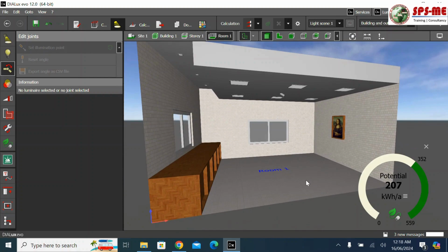So normally before you do the calculations, you need to set what lux you require. So I did not set that over there. If I did not set anything, by default it will select 500 lux. Otherwise you can go and select that. That we have discussed in the previous class. So you can go to the spaces, and from there you can select the utilization profile, and you can select what you need. Accordingly, whichever utilization profile you select, the lux will be selected. If you don't set anything, by default 500 lux will be taken. So now my calculation is with 500 lux.